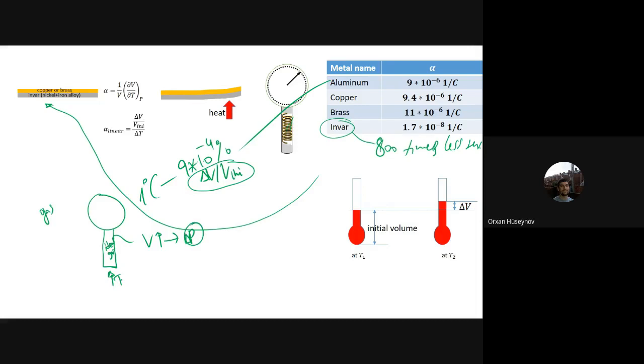But the reason is delta T. You can see the pressure change, but the delta T is the reason. There are intermediate steps, which is the volume change, but the final response is delta P. So you have the relationship between delta T and delta P, and therefore you can find the temperature inside the room by knowing delta P. Okay? So you know pressure, and from that pressure you infer the value of the temperature of the room. Okay? That is for ideal gases.